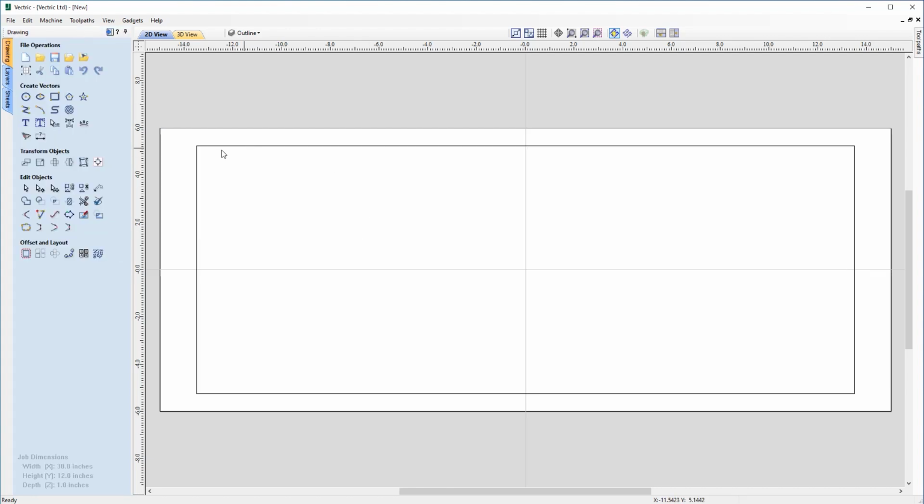So now we've got our outline on the outline layer, we're going to want to look at creating the top and bottom grooves for our quatrefoil. With that, we're just going to come back up to the layers menu, and choose this option to add a new layer, and this one's going to be called top and bottom grooves. And again, we'll just make sure that that's the active layer, so you can see that highlighted.